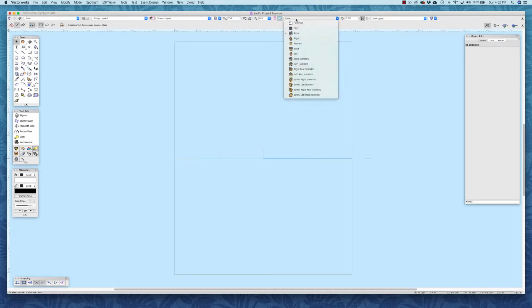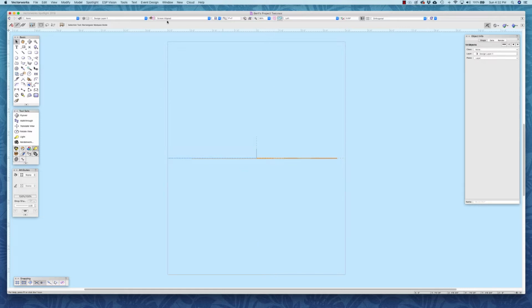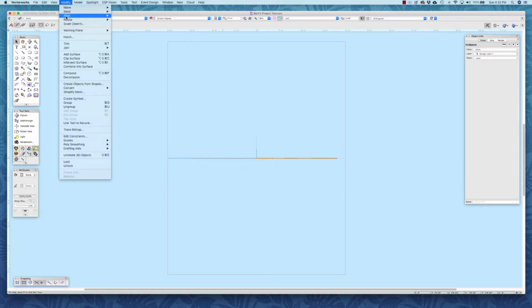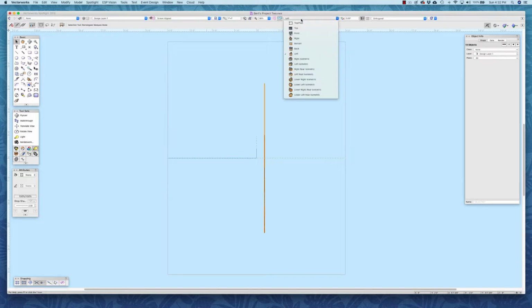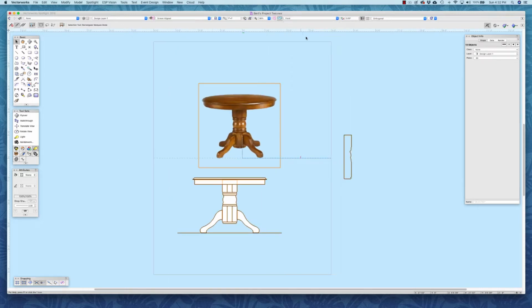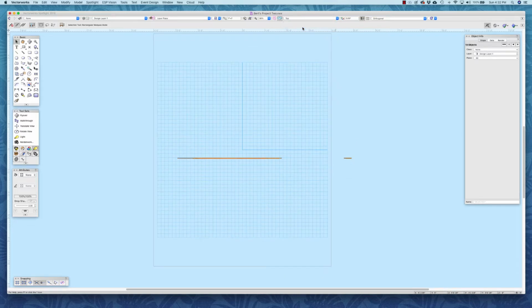Fortunately, this is easy. We're going to switch to left view, select everything, modify rotate right, and then back to front view, and voila, it's back. If we happen to go back to top view now, we'll see that we're only seeing a line in this view.